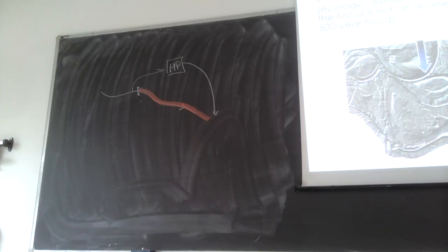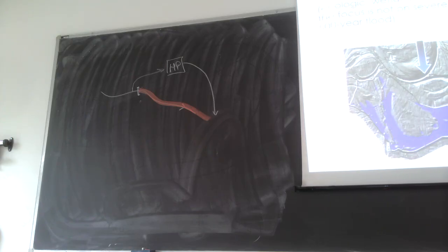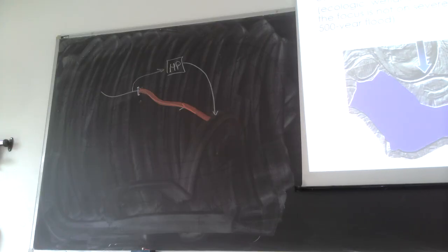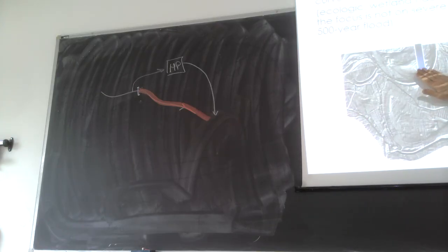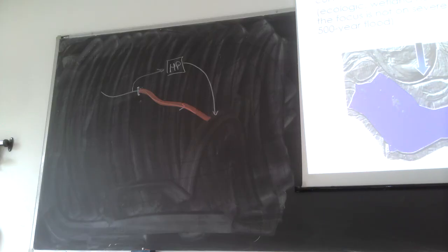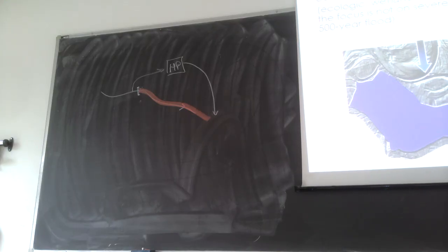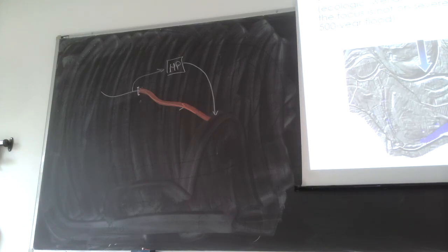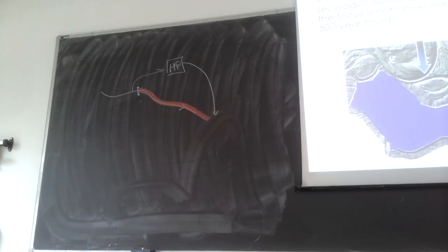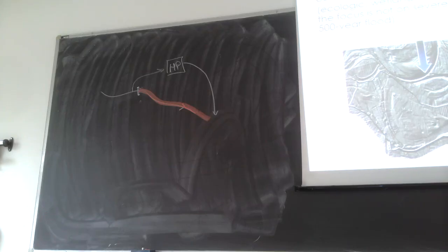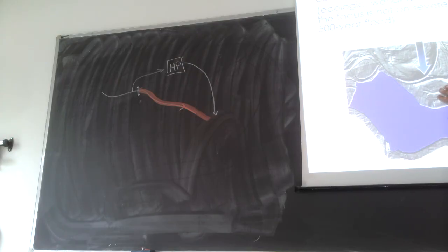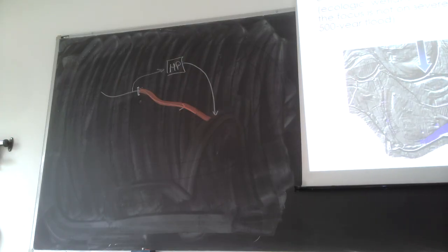Then you can, with a flow duration curve, associate the stream flow to a given duration. Joining these two diagrams can be summarized in a single diagram that tells you the water level as a function of the duration. Let's suppose that in this area you have an orchard with fruit trees that are particularly sensitive to the presence of water, and they can stand water only if it stays there for, let's say, 2 weeks in a row, 20 days in a year, okay?